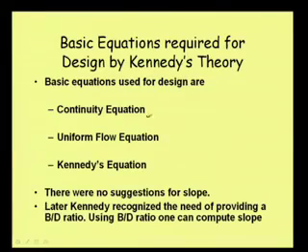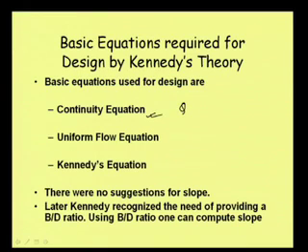Well, the basic equations that are used for design: the continuity equation will be required. That means along with Kennedy's equation, we will require some fundamental equations for the design of the canal. And the continuity equation, as we know, is Q equal to A into V.